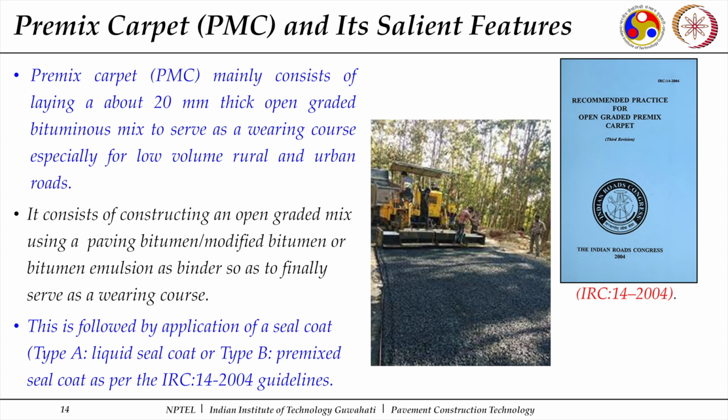So it is premix carpet, that means I am doing some premixing, and it mainly consists of laying about 20 mm thick, and here it says open graded. Now this is the gradation I am picking up. Actually I'll be using single sized aggregates, and when single sized aggregates are used, that makes my gradation open. So that's why it is referred to as open graded premix carpet.